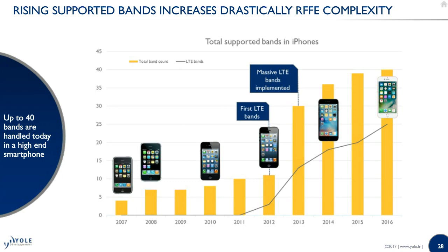So we began at 4 bands and we went up to 30 bands, and nowadays up to 40 or 43 different bands depending where you are located geographically. So you can really see that 4G really brought complexification, a higher number of bands to handle in the same front-end module, and that's where the complexification really started.